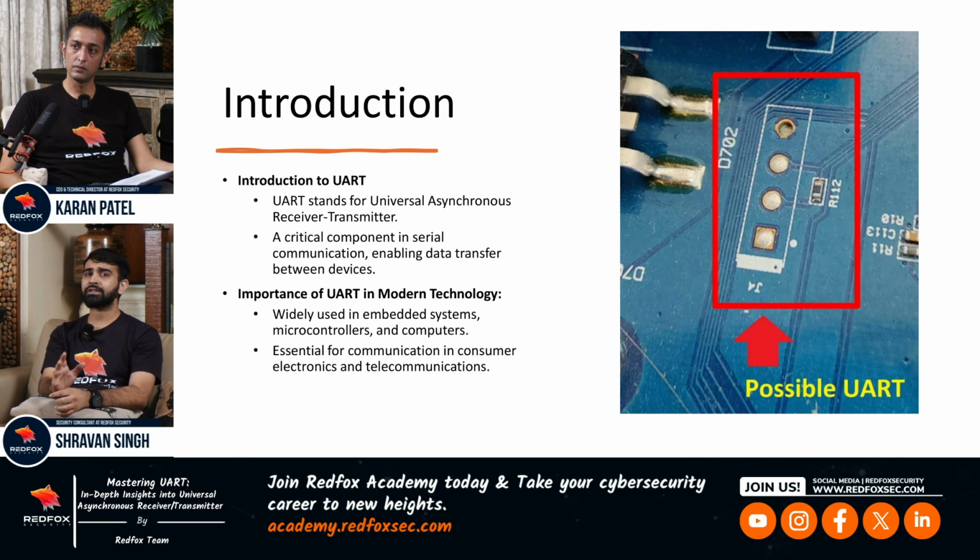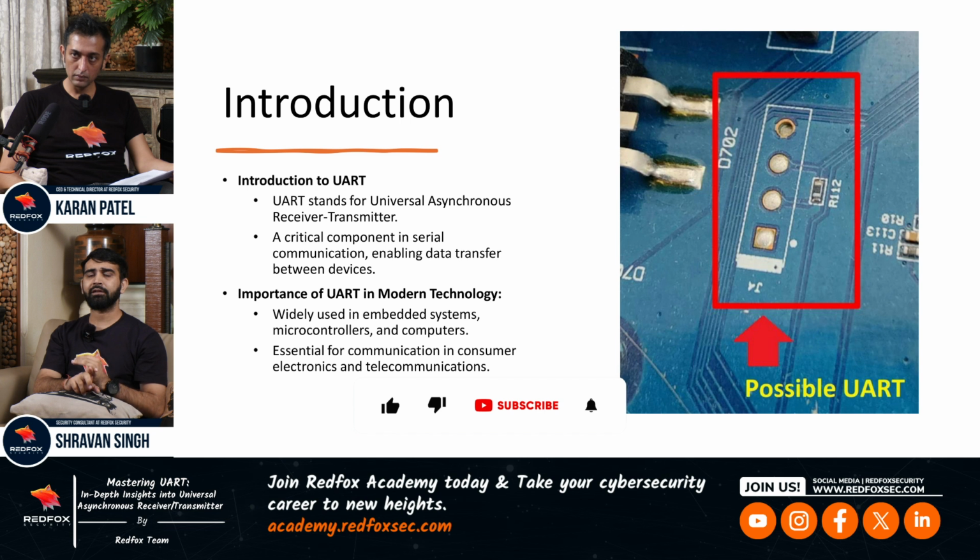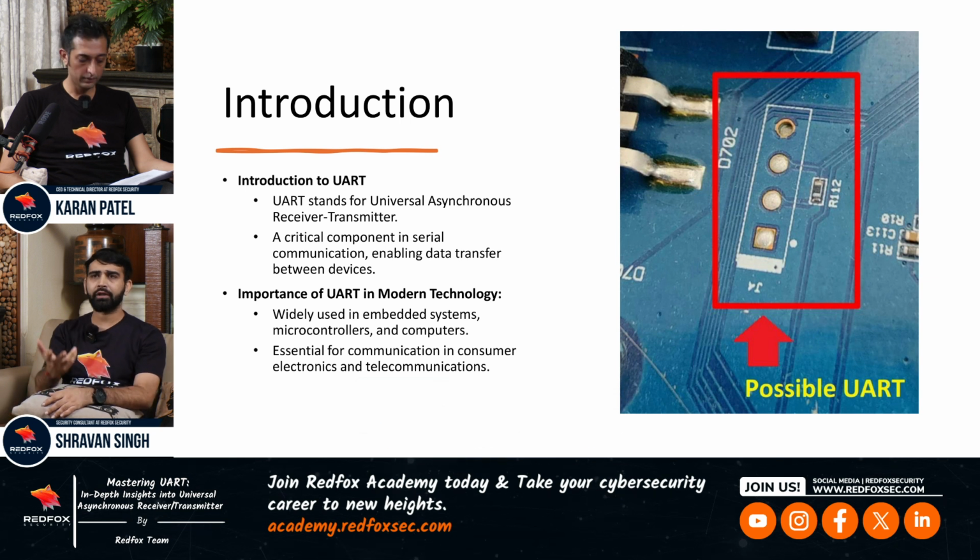UART consists of 4 pins: RX, the receiver; TX, the transmitter; GND for the ground; and VCC for the power supply. The power supply depends on the device, 3 volt or 5 volt, depending on which device we are using. These are the devices we use in modern technology.